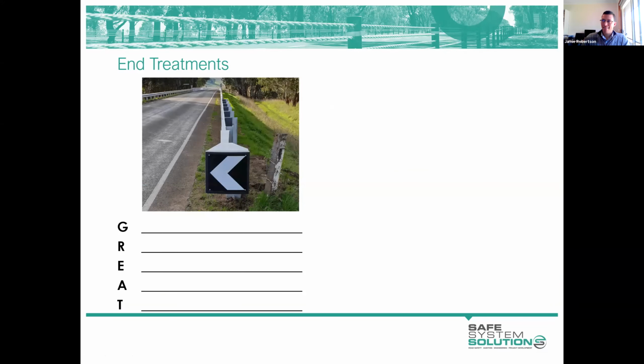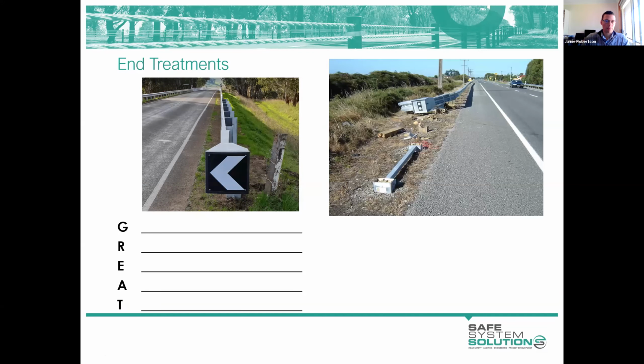We've already gone through what GREAT stands for, Gating Redirective Energy Absorbing Terminal, and there is one of the other newer MASH products. That's the MSKT. So when struck, it's an extruding type terminal. It's going to spit the rail out to the side. So that's another reason why it's nice to provide a run out area, so that when that rail is extruded, it can operate free of any objects that might be located behind the barrier.